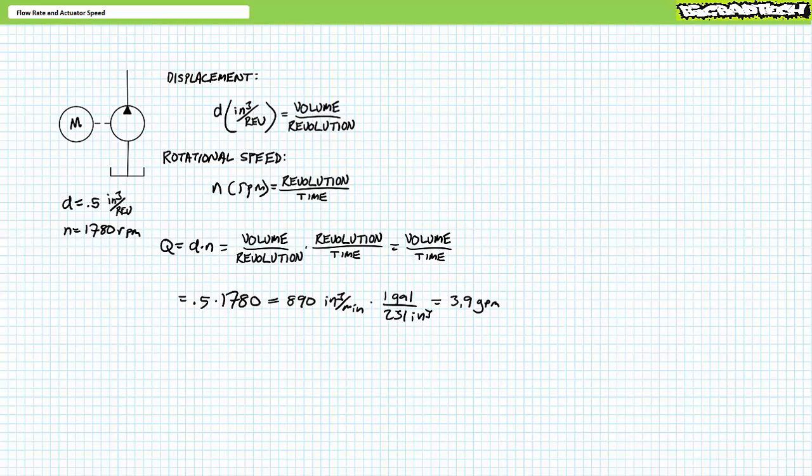to vary flow rate. Lastly, do not labor under the mistaken impression that the property of displacement per revolution is a fixed and ever constant value, even for fixed displacement pumps. The displacement figure specified on a pump's datasheet is a single snapshot at a single operating condition known as the rated condition, i.e., what the pump has been designed to do. If the pump is being driven in excess or below its rated condition, one might expect displacement per revolution to vary. For example, let's say a hydraulic system is exerting a lot of force and necessitates super high pressures.